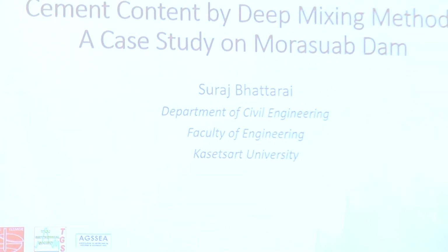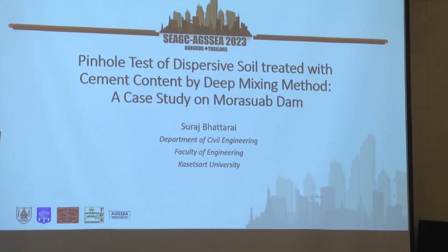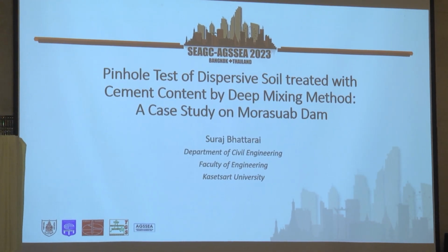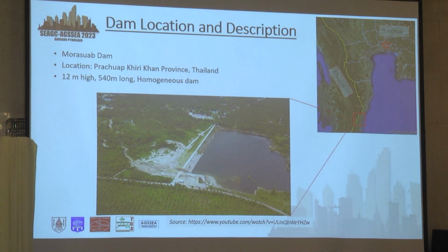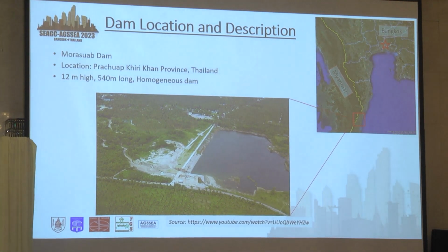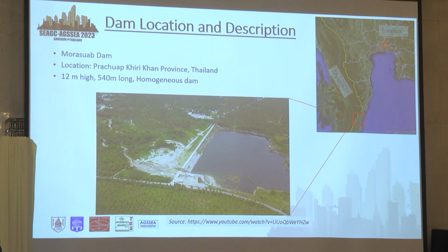Thank you very much to the organizing committee for this platform. So my research topic is the comparison of the pinhole test of dispersive soil treated with cement content. This is one of the case studies of the Morasup Dam, which is in Thailand. First, for the location of the dam: the dam is situated in the southern part of Thailand, in Prachuap Khiri Khan province, almost 400 kilometers from Bangkok. The dam is a homogeneous dam, 12 meters high and 450 meters long.